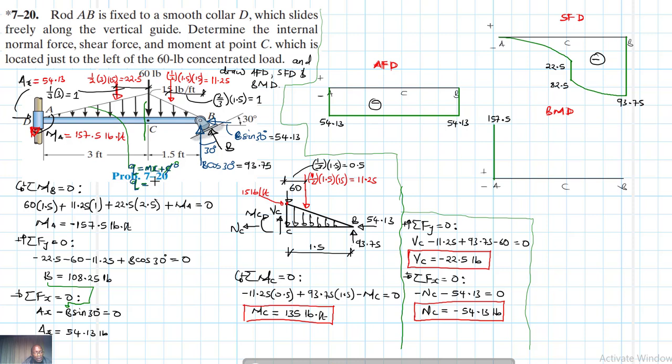So the change in y is just 15 for the distributed force, and the change in x is 3. Therefore this just becomes 5x. So this is the function that governs the load. If you make x equal to 0, the distributed force at A is 0. And if you make x equal to 3 at C, the distributed force is 15. So that's the equation that governs our shear. We are looking at A to C, so our q is equal to 5x.